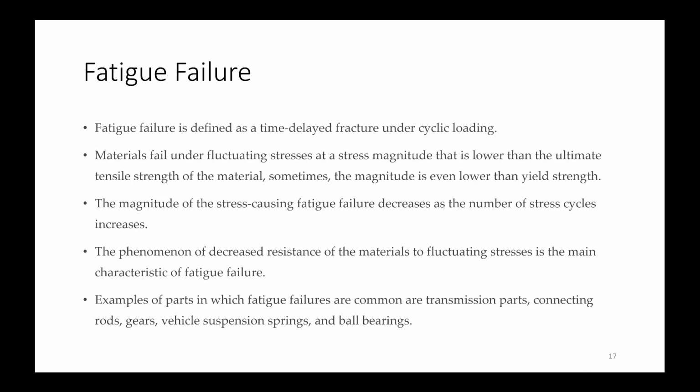Fatigue failure is defined as a time-delayed fracture under cyclic loading, and these materials fail under fluctuating stresses at a stress magnitude that is lower than the ultimate tensile strength of the material, and sometimes even lower than the yield strength.